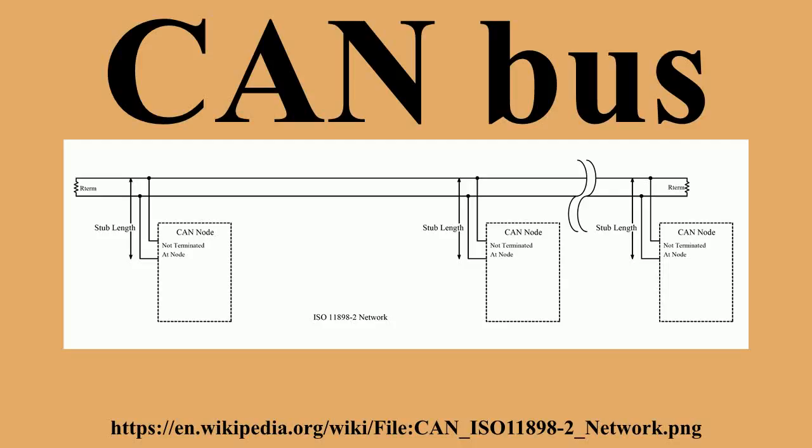The complexity of the node can range from a simple I/O device up to an embedded computer with a CAN interface and sophisticated software. The node may also be a gateway, allowing a standard computer to communicate over a USB or Ethernet port to the devices on a CAN network. All nodes are connected to each other through a 2-wire bus. The wires are 120 ohms nominal twisted pair.